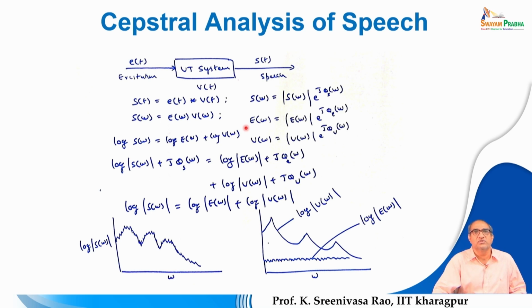For that we can use the spectral information of the vocal tract and excitation separately. But using FFT, we get a combined spectrum, the product of these two spectra. Sometimes you can directly use these spectral characteristics for discrimination, but sometimes if you analyze the excitation part or the vocal tract alone, you can see specific discriminative information. In that context we need the individual spectra.